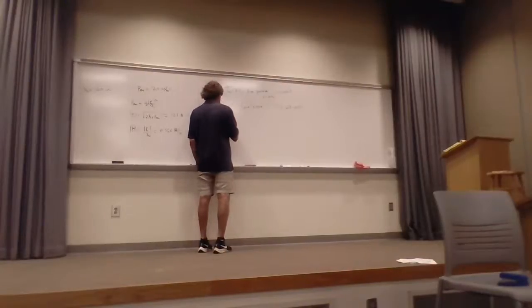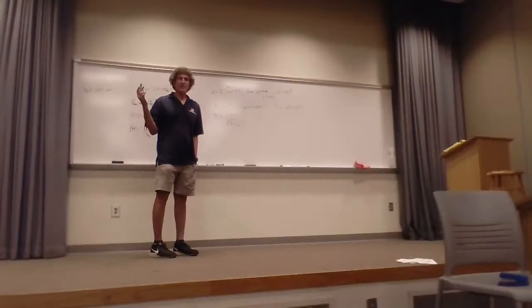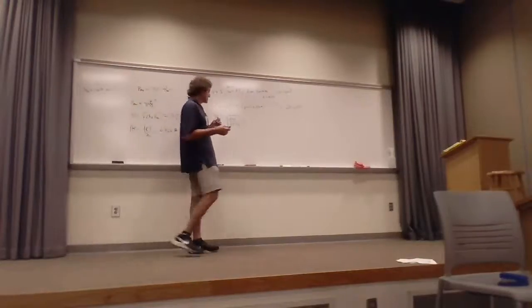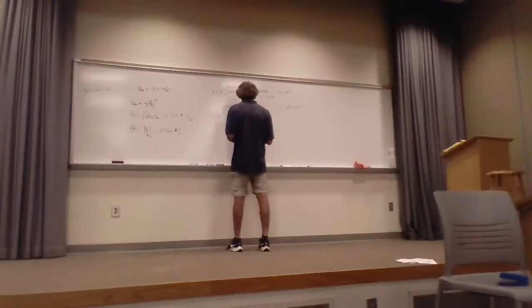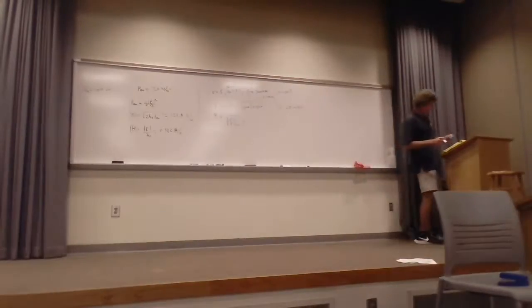And eta, the formula is the square root of J omega mu over sigma plus J omega epsilon. Here, you couldn't assume this was a good conductor or a very lossless dielectric. It was both. You had to run the numbers on this one.